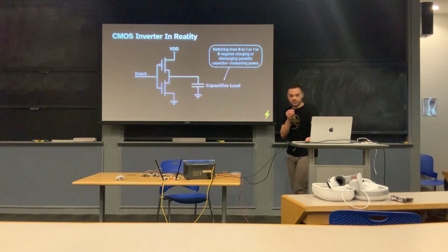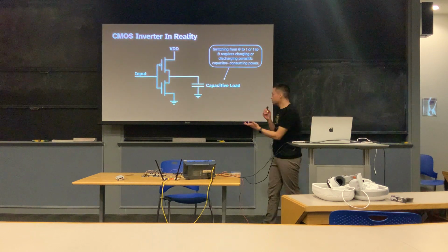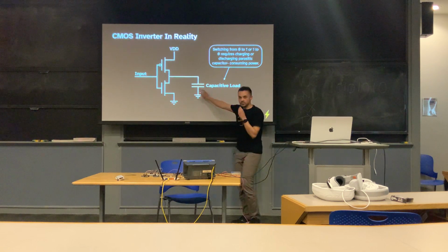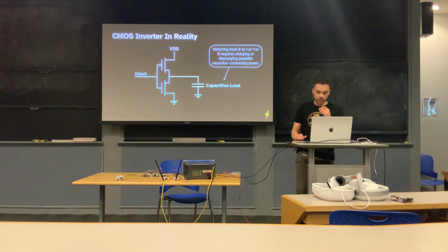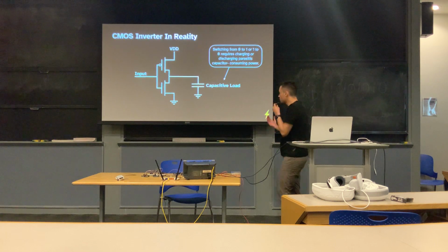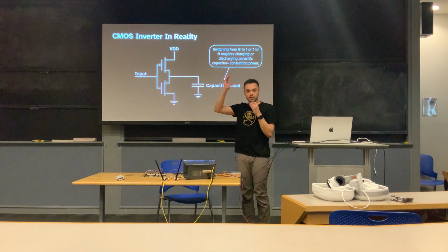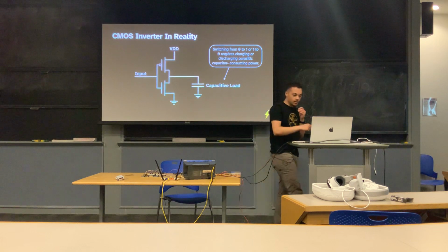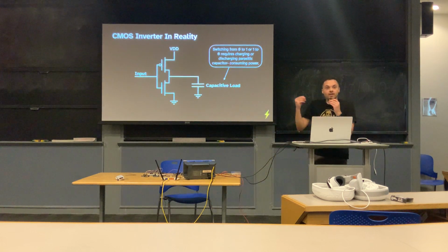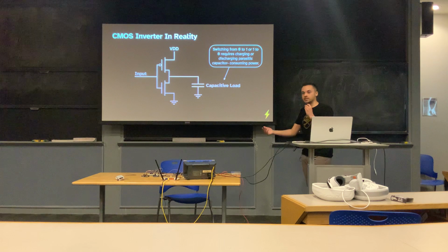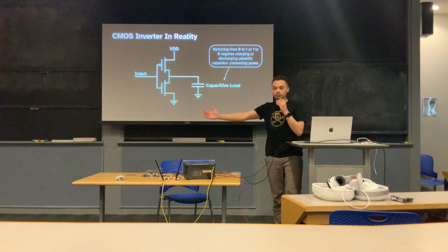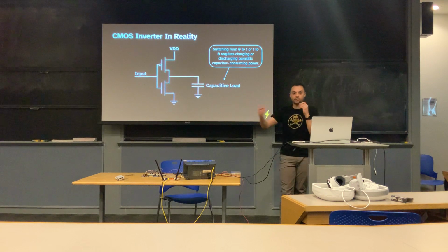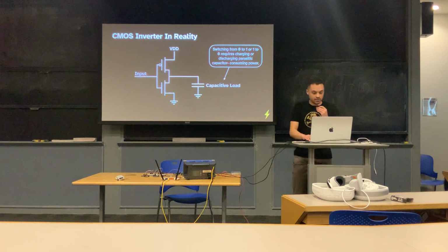And so switching from a 0 to a 1 or a 1 down to a 0 requires either charging or discharging this capacitor. You have to do it. That is a law of physics. And so that'll consume power. The more capacitors you're switching, the more switching power is going to increase in that instant. So different parts of the chip are going to use different amounts of power. By looking at how the power varies over time, you can learn high-level information about the chip's utilization over time. That's what we were able to do with that simple power example.